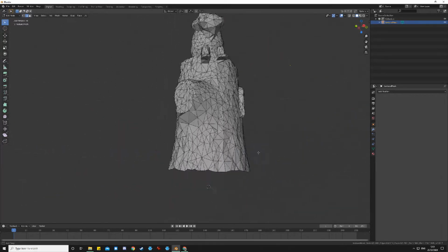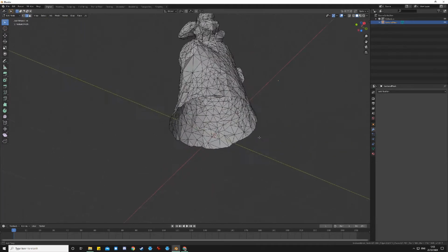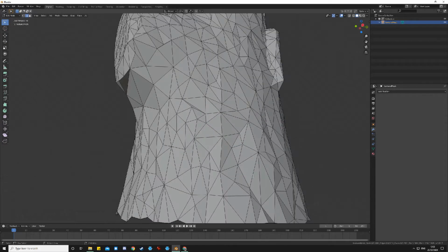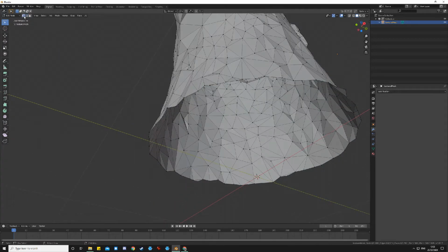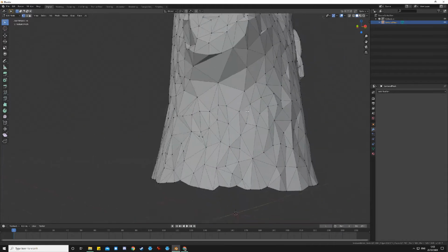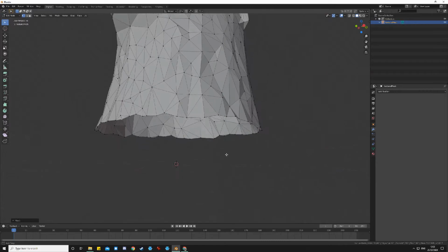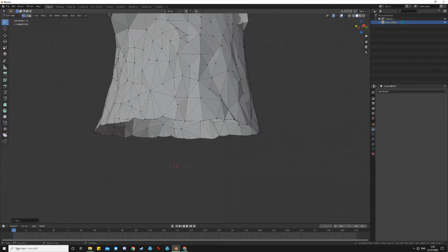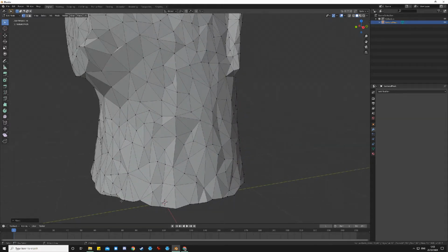Great, that looks brilliant. So now I would do a repairing kind of trimming section where I'll start looking at the model and seeing bits I want to repair. So the first thing I'll probably do is go around the bottom of this tree trunk, and I'm going to grab the odd vertex, press G, and just move it down. This will just hopefully create a relatively straight circular edge around the bottom of the tree trunk, so that I'll be able to fill it.